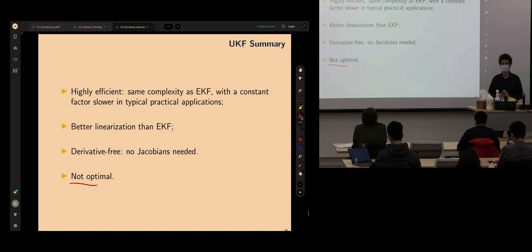That's a class of error state EKF. Instead of linearizing the model itself directly, calculate the error dynamics and then linearize the error, because covariance is basically a centralized moment, right? You may as well centralize it around the true state. And when you do that, for certain problems, the error dynamics becomes independent of your state.